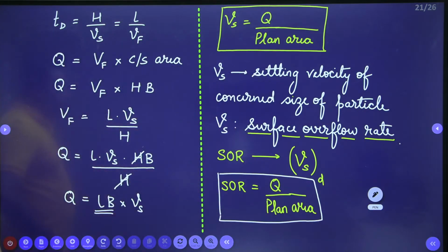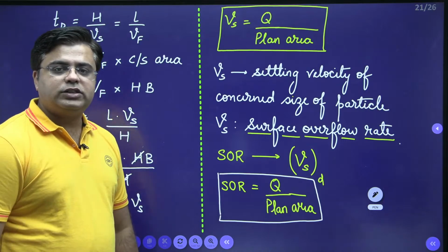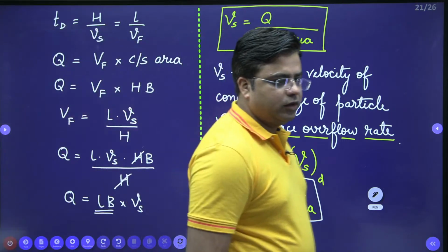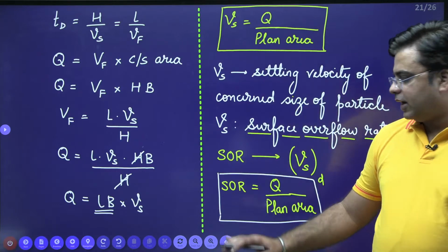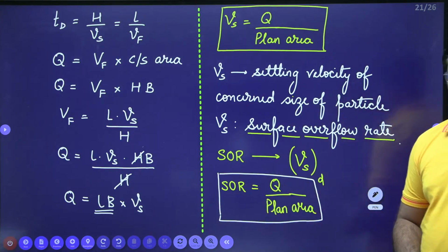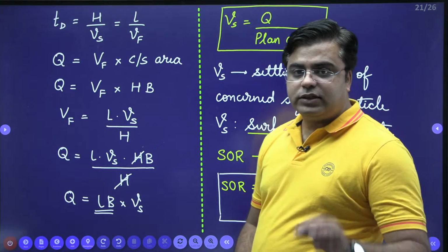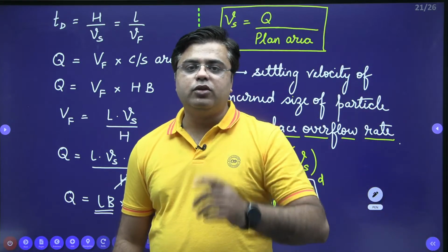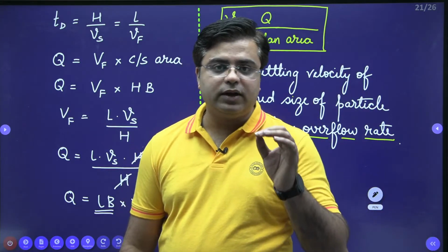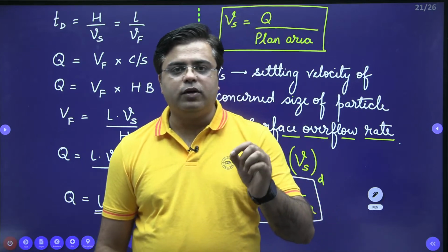This surface overflow rate is equal to discharge divided by plan area. So you can see a lot of questions that are asked using this expression also. So whatever we are discussing is very important related to GATE preparation. Whatever is written on the board, every word is important.